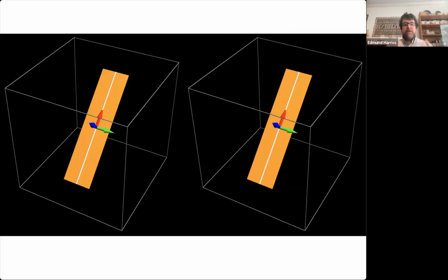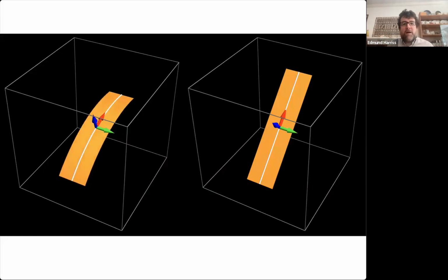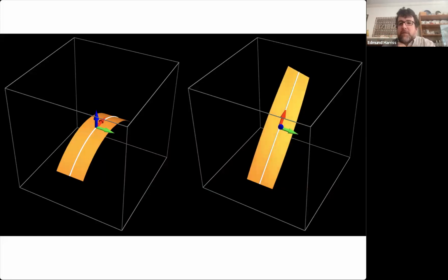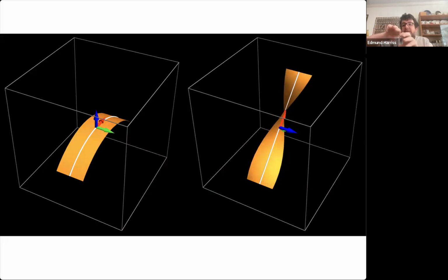And if you take pieces of metal, they don't really mind bending in this direction, but what they don't like to do is twist. So if you've got a piece of metal, you can locally bend it in different ways to create a curved path without actually changing the geometry of the surface.